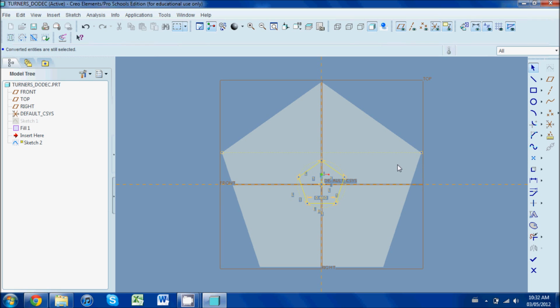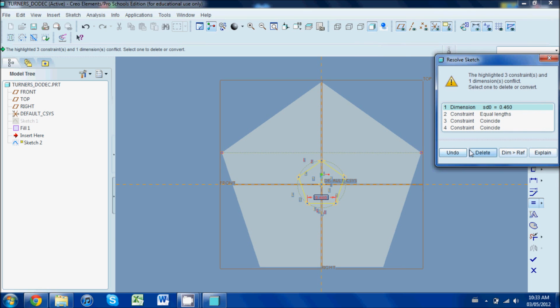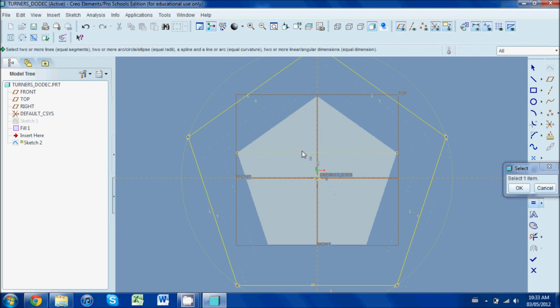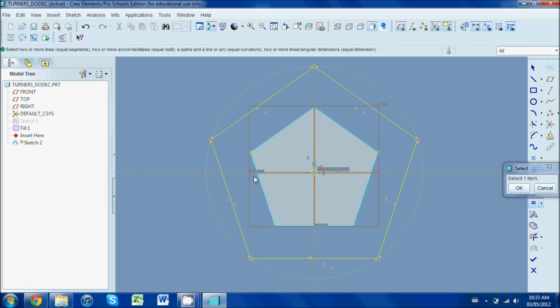but what they will do is allow you to take references, and in this case we want this base edge dimension to be the same as this, so we can use a constraint which will go over here. We want to pick equal, so we want to say that this line is equal to that, and we're going to delete that constraint. So now if we zoom out, you can see that these points are in line with each other, and if you don't believe me, I can draw a line for you. They're perfectly in line with each other.